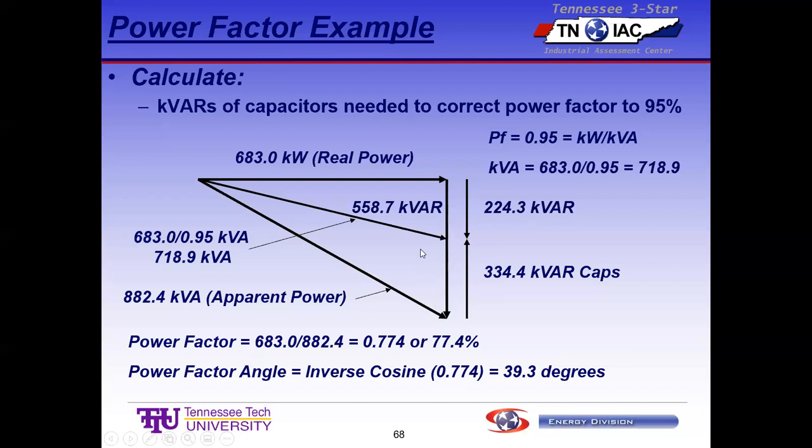And then the current reduction goes from the capacitor all the way back through the MCC, all the way back to the power company. And all of a sudden, hey boss, we had to spend $2,500 on little capacitors, but we don't have to spend $50,000 to expand the capacity of the MCC. And you get patted on the back, and the guy says, I'm going to remember you at bonus time. So that's the other motivation other than to avoid the penalty. It doesn't come up every day, but it's not uncommon to need to unload an MCC.